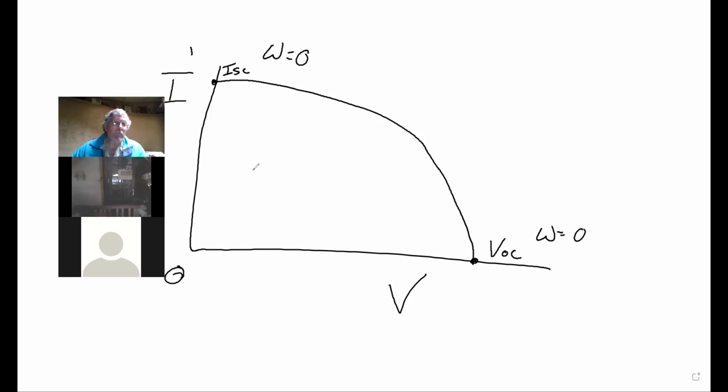So neither of those conditions is a good condition, obviously. So the system will be broken. But we use the ISC as the maximum. So when we're doing our design work for wire size and the like, we'll use the ISC because that's the theoretical maximum worst case condition.